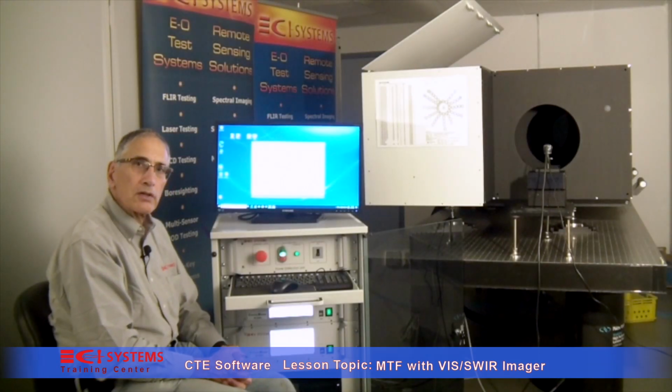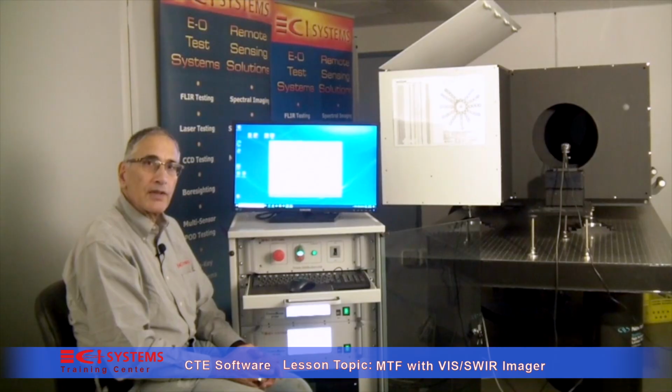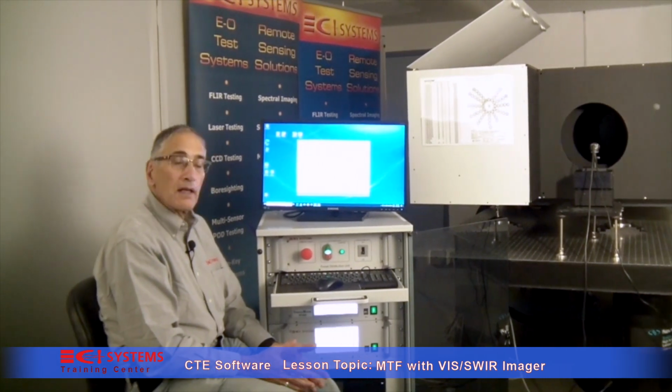In the following sessions we're going to talk about running the MTF test in the CTE and in general. In order to run MTF, one basic variable we need is called IFOV. IFOV is directly connected to the resolution that we can sample with MTF, or the maximum resolution, or what we would call the Nyquist frequency. So we need to know this value in order to be able to plot the MTF.